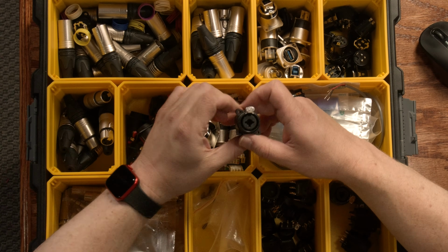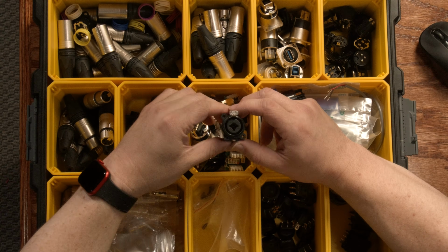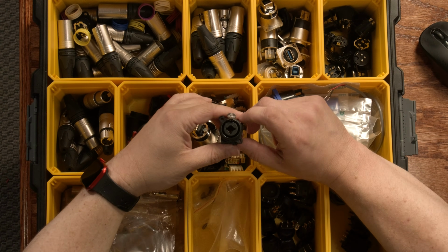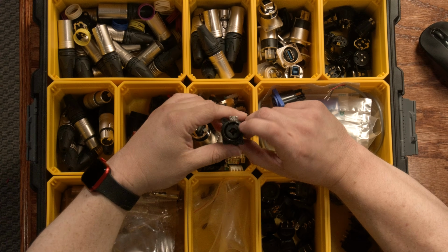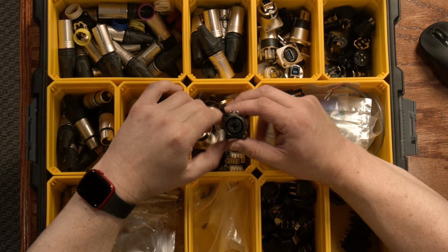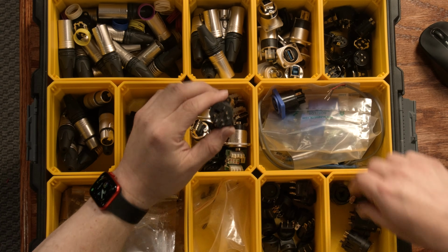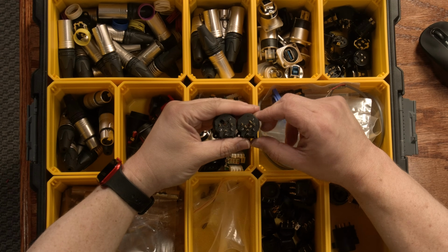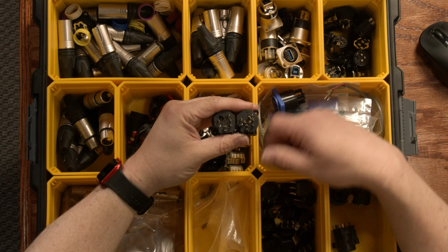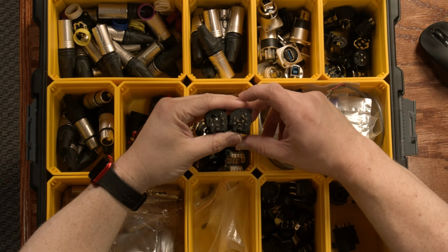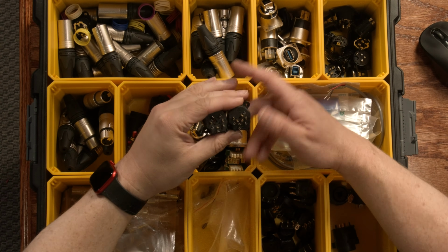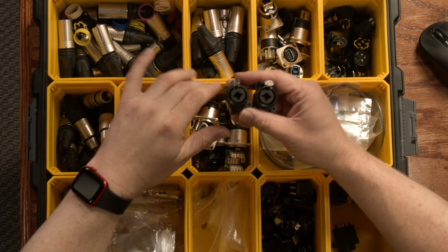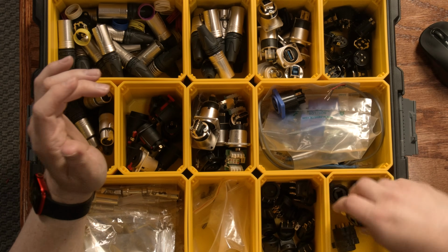Also, we have these. This is a Neutrik universal combo jack. So this one will accept either XLR male or TRS. You can do either one. And they have separate connections on the back, and they have multiple different versions of these. So you can see this one has more connections on it. This is a switching one, so you can actually have a signal pass through by default until it's interrupted by plugging in a plug on the front. So numerous different variations on those. And these are some of my favorites. These things work great. It's nice having a lot of variety there.